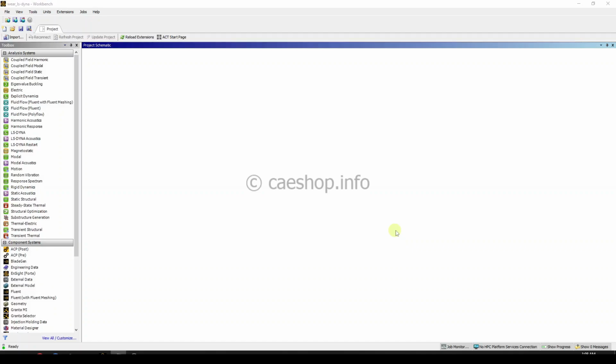In this video, I would like to introduce to you how to perform the wear simulation problem using Workbench LS-DYNA. Workbench LS-DYNA will be used for pre-processing purposes, including building the assembly, setting boundary conditions, and the wear model. Then, LS-Reader will be used to read and display the wear result.